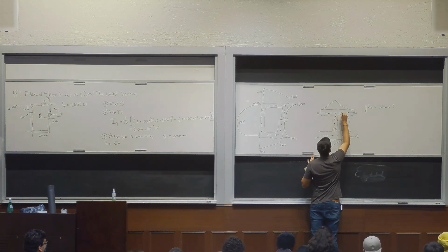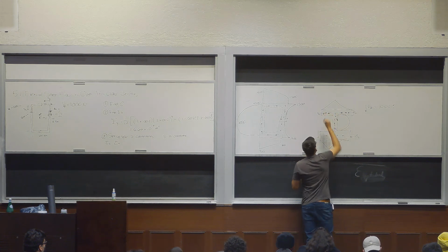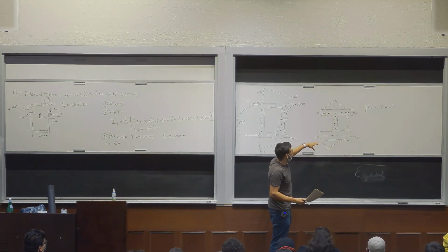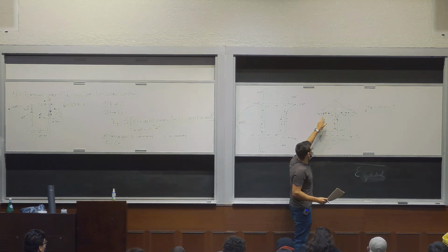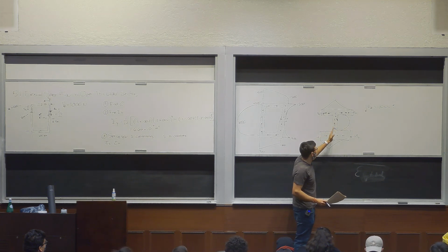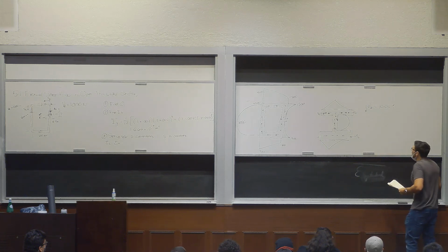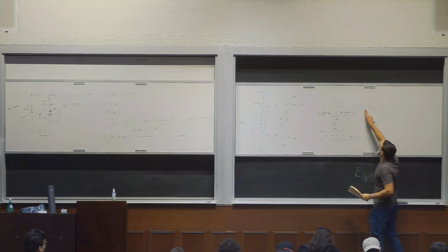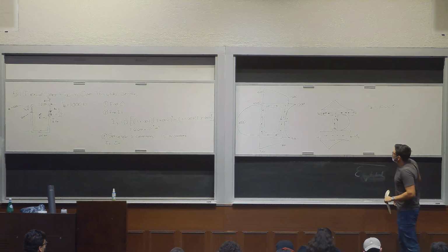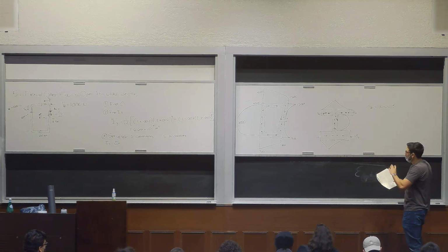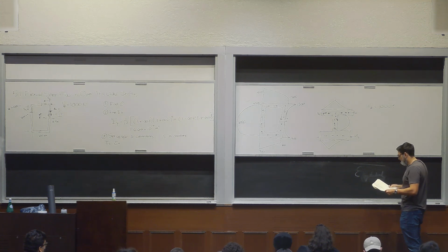And the direction of the arrows always kind of makes sense. When you're thinking about shear flow, it's as if it was water flowing. This one, for example, wouldn't go to the right. It's like if you have a stream going this way, it would split up, and these both would come together there. So intuitively, the drawing of the shear flow arrows should make sense. So that's a case where you would have multiple starting points for your S coordinate.